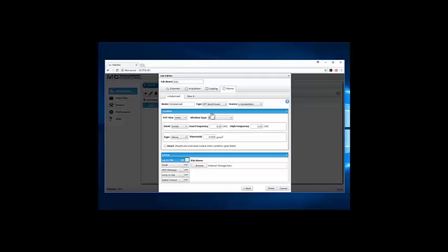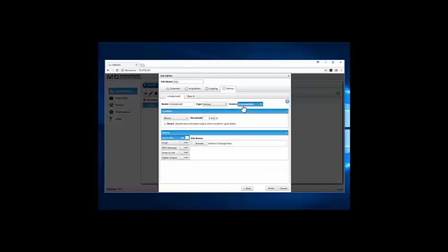I'm going to keep it simple for this alarm and choose an analog alarm based on the X acceleration, and set the condition of the alarm to above 1G. You can also choose what action you want to take when the alarm condition is met. I want to log the alarm to a file. Let's call it fan alarm.